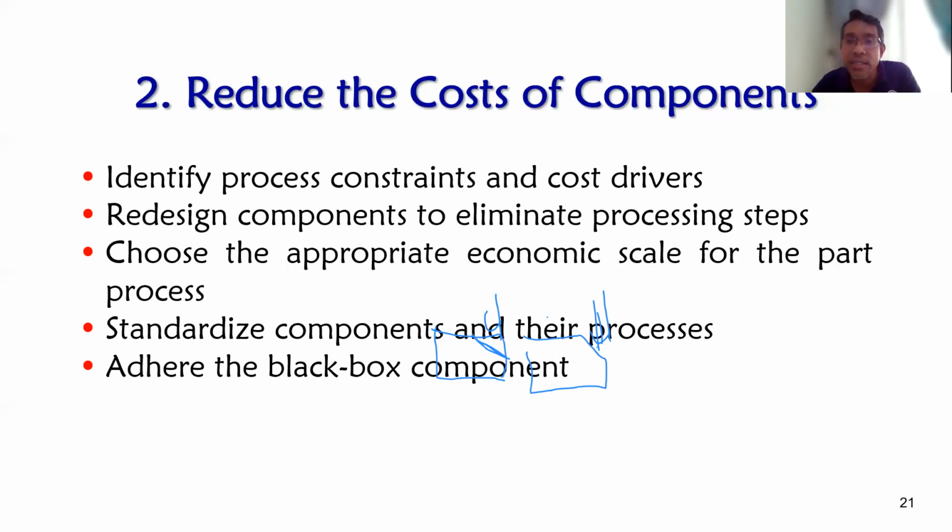The designer may need to understand why they need that tolerance. The designer may specify the dimension and the tolerance, what they need. For a difficult tolerance or specification that is difficult to achieve with accuracy on the existing machine, they need to avoid that.